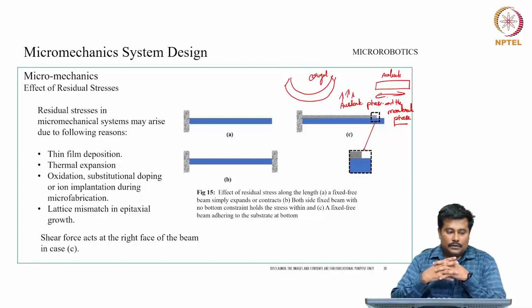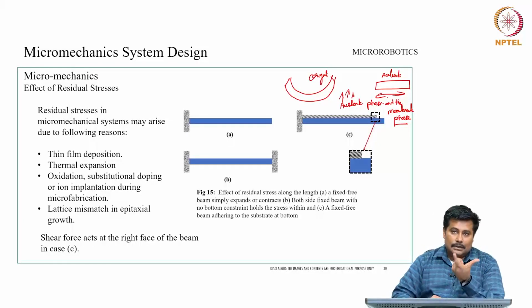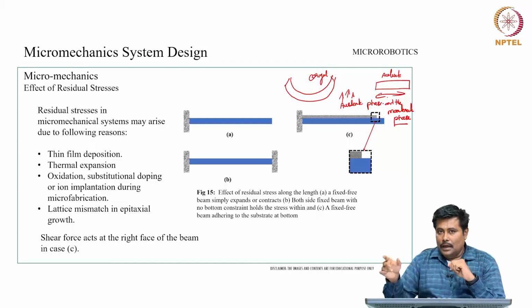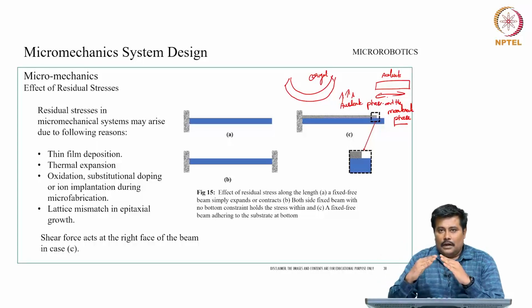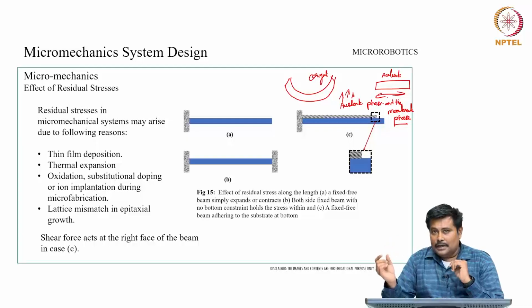Now, if we closely observe, in this particular case also, we are trying to use these shape memory alloys for high frequency actuations, ideally in micro robotic systems. We try to deploy it for stick slip motions, or we have also seen peristaltic motions. Similar peristaltic motions can be evolved with such micro robotic based systems. So, there is going to be continuous actuation and deactuation employed within a short displacement, so that it has a restriction towards a particular frequency.